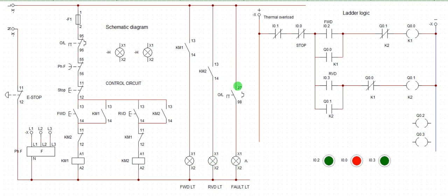Okay, because I have overload here. All right. So this one will illuminate when forward operation is being energized. The same way this one will illuminate for backward operation. Then I feed them. Sorry. So we are going to introduce the auxiliary bit. Put them here. Put the auxiliary bit here. And put this one here.